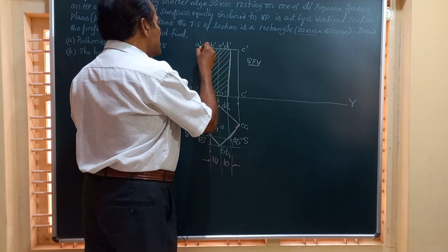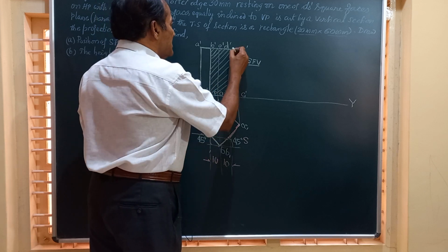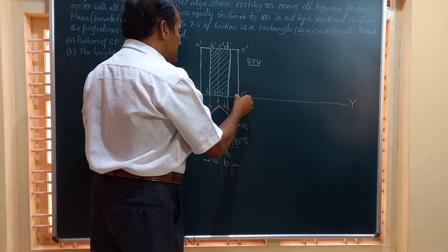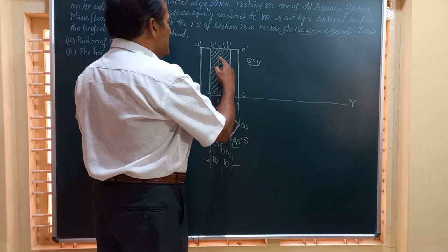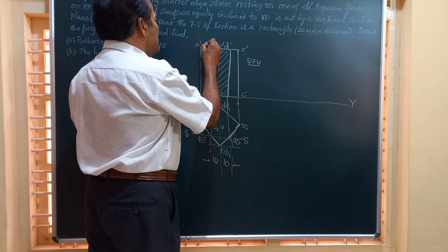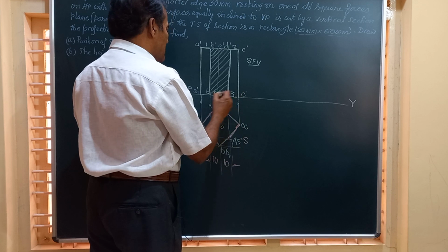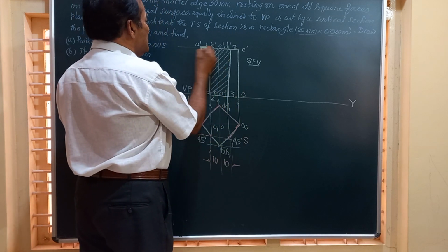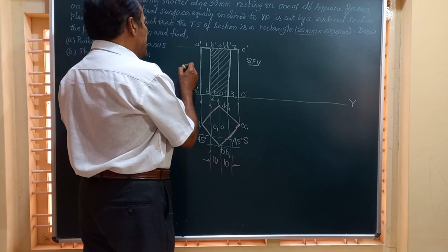We can darken the remaining part of the solid by completing the front view of the solid like this. Friends, here you can see that the true shape is this rectangle. I will say 1, 2, 3 and 4 is the rectangle, and this has got a dimension 20 millimeter by, this is going to be 80 millimeter.